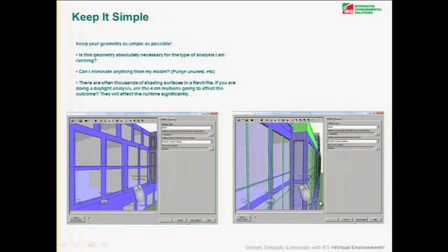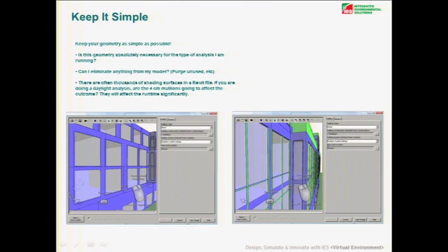And make sure that when you are setting your level of complexity, it's coming through. So the different levels of complexity, this is the most simple. It means it's completely ignoring mullions, which would then mean the mullion family is not going to come through. So you would have to use the roof family to bring pieces through. And this is all very specific to a Revit user. If you only use the VE, all you'll know is that I need to redraw it, basically, because it's not there.